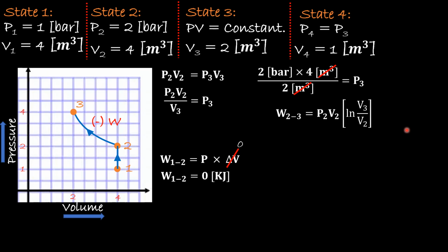2.27, where the polytropic index is 1, just like this, PV equal constant, where we took the integration of the work, pressure times change in volume, and we replaced the pressure by rewriting this equation where we solve for pressure in here, volume goes to the other side, so pressure will be equal to constant over volume. And since this is constant, we can take it out of the integral. So you can see the whole process and how we did this integration to reach this conclusion. And I will try to add a link to this problem somewhere here.